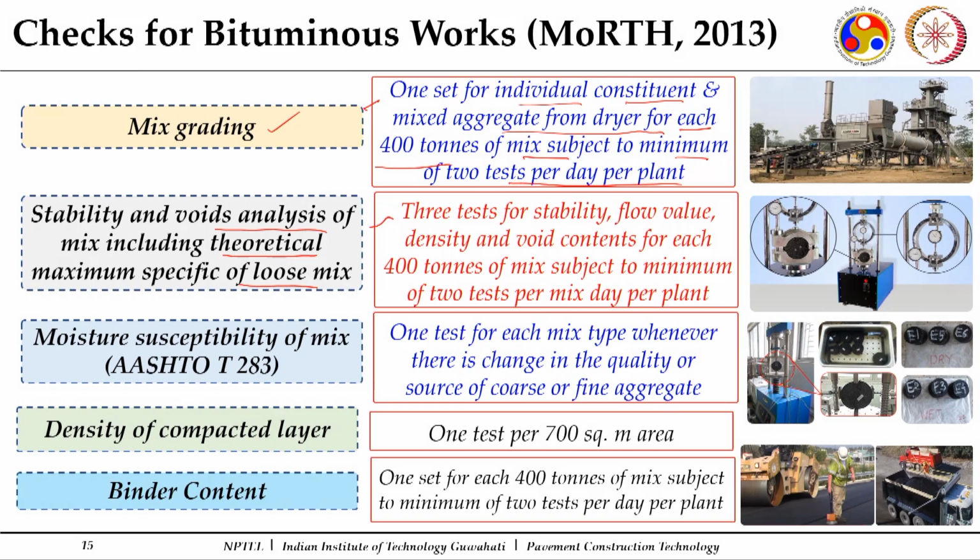This we discussed during the course of bituminous mix design. What is the strength it carries, what is the load it has, what is the flow value, how much is the density we are able to achieve out of it, what is the void content at the given number of compaction blows. So we are trying to ensure whether that combination is now able to give you what you have designed.